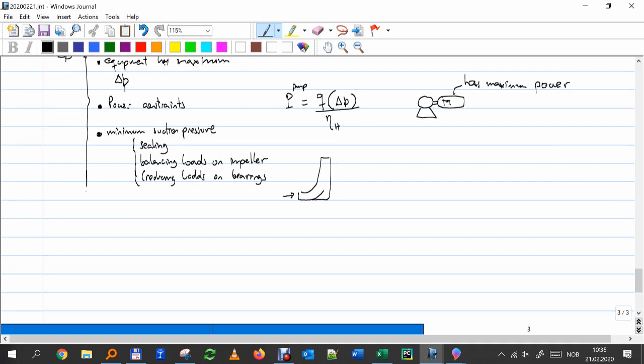We typically have an operational map, okay? That's what you're going to work with today. For compressors and pumps, we have some operational map of the equipment. We have some region of delta P versus rate that both pump and compressor are able to operate in, okay, within that region. And simply you cannot go any place outside of that map, okay?